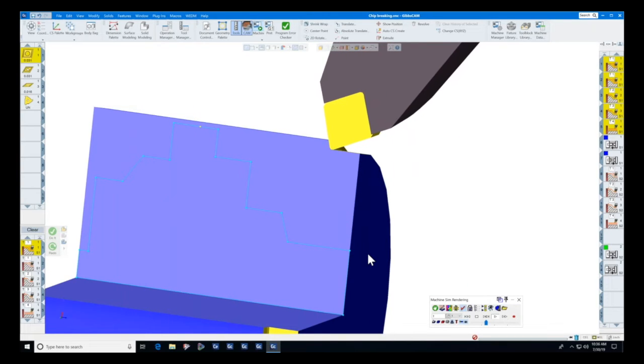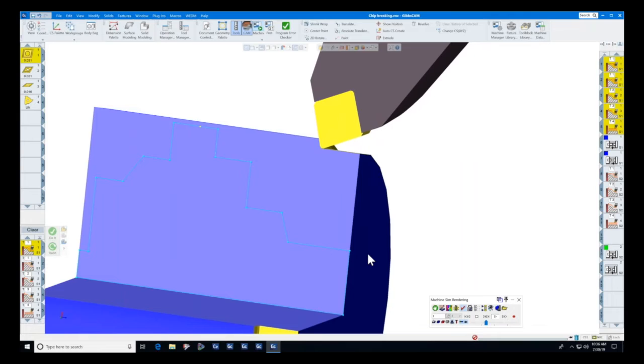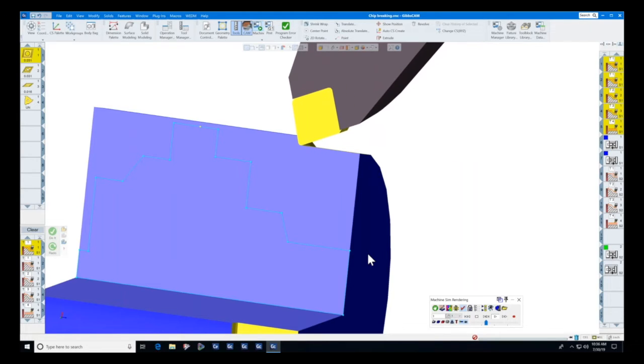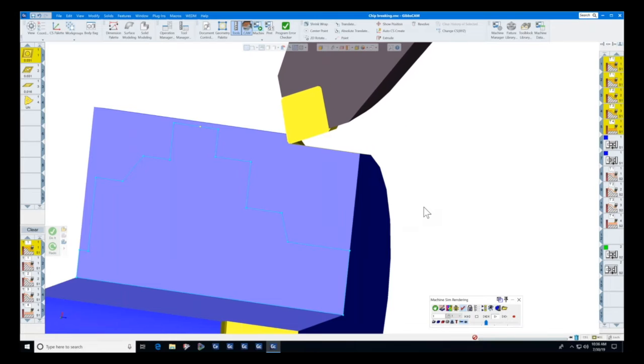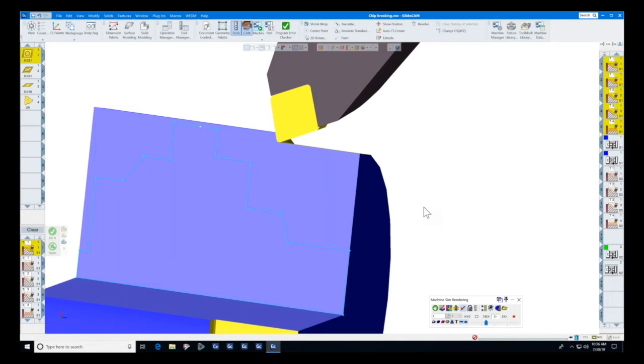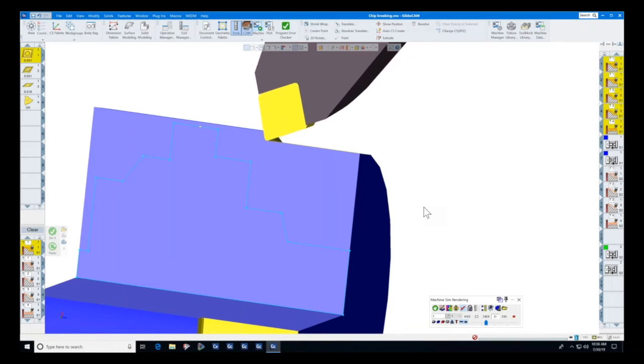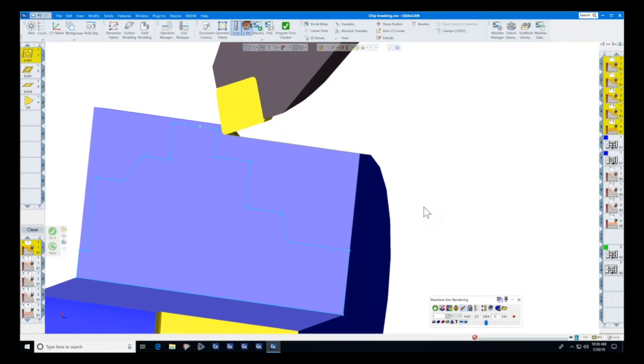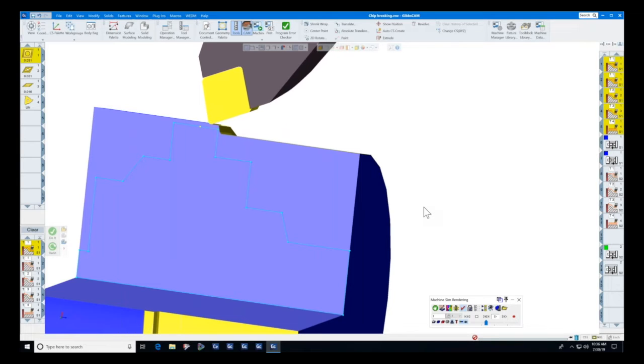So yes, we are cutting, we're pulling back at an angle so that we don't drag the tool across the workpiece, and we're actually forcing the chip to break. And in many cases, this saves us a lot of time, because of the time that you spent opening the door and pulling the bird's nest off the turret, and then the bird's nest gets wrapped around the part, wrapped around the chuck, wipes out your probe in your turret, and you've got a terrible mess on your hands.